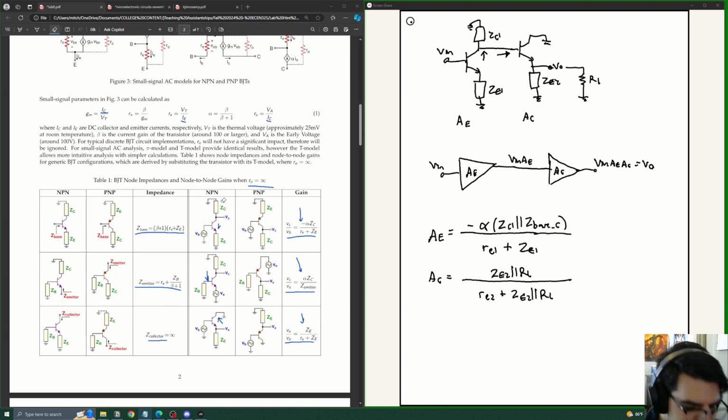But now we can just model this as two amplifier symbols with the input impedances looking into them, and the analysis is as simple as: write the gain of each stage, see how the gain equations are affected by the input impedance looking into the next stage, and then multiply these equations all together, and boom, you've analyzed your circuit. So we've avoided the algebra with the small signal model, and you've very quickly analyzed this multi-stage amplifier with the equations given here, just because we had derived what these gain values are.